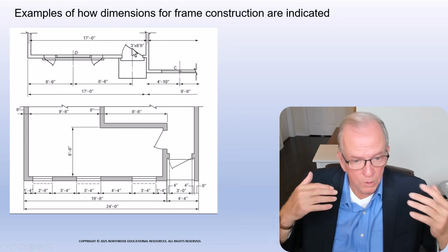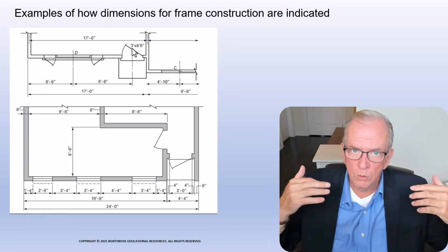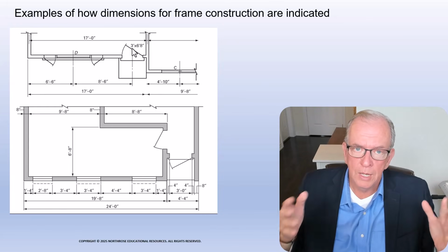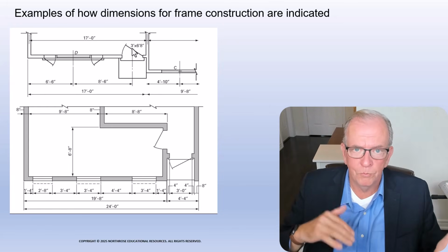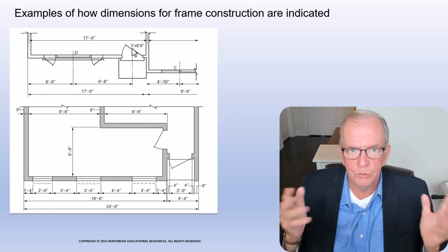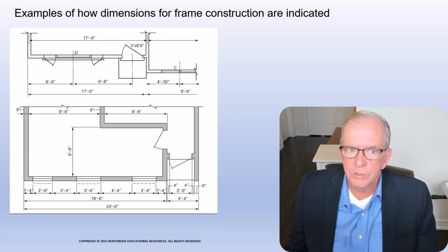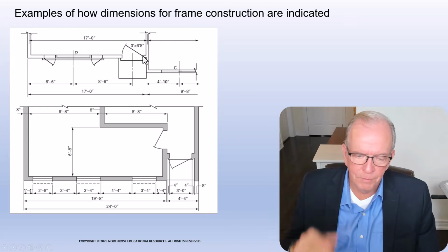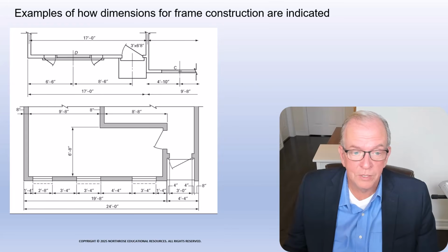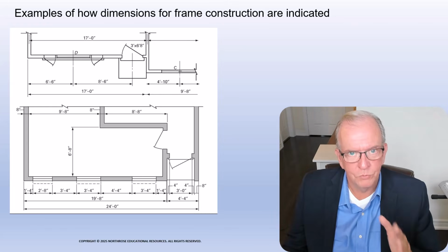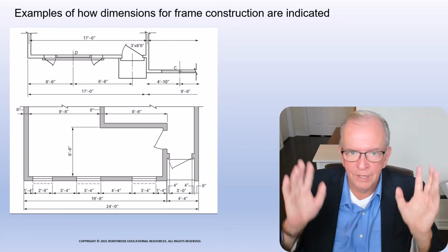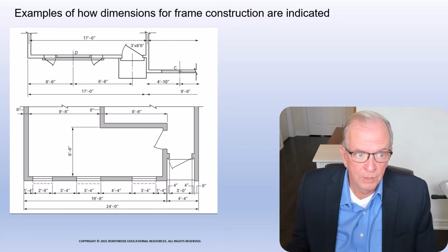Because a lot of times with construction, we're ordering pre-hung doors, and so you want to order them the right way, whether they're right or left. When I was younger, I remember my dad had me measure up all these doors. It was for this apartment building. They were steel doors, custom made. And I messed up a number of them, what was right and what was left. And I always remember the door vendor telling me, just remember, butt to the butt, right hand, left hand. And after that, I never had it wrong.